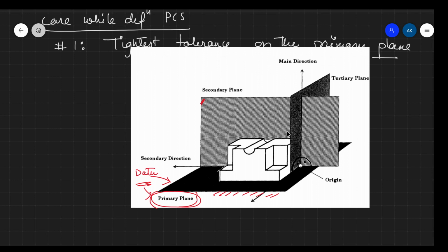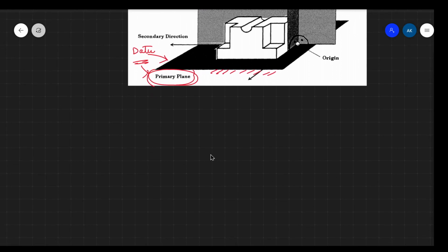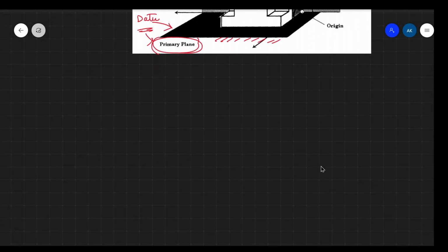One is related to machine movements, which is the machine coordinate system. Another is related to parts, in which the coordinates of parts are taken, and that is called the part coordinate system. And the relation between both of them is: x of part is some rotation matrix times x of machine, this is a vector, plus the translational vector. So this you should know.